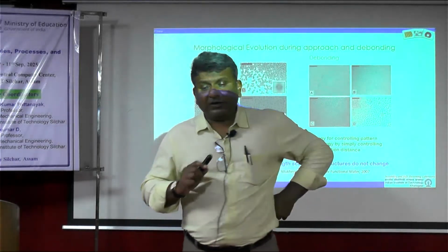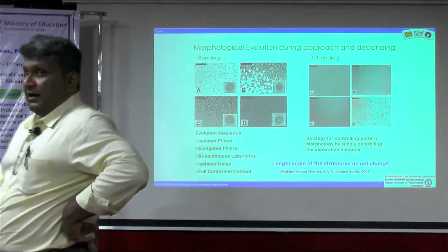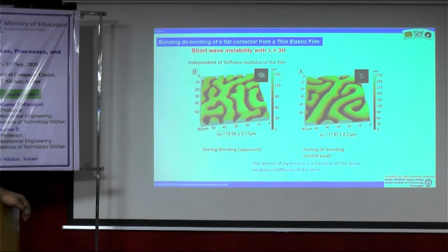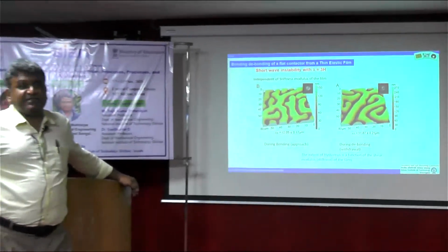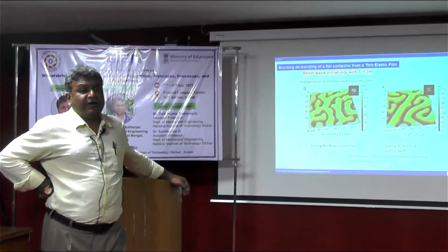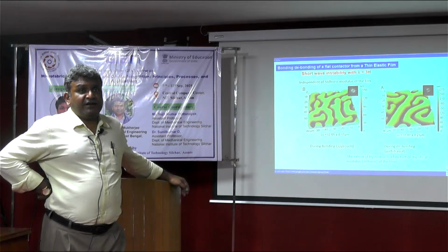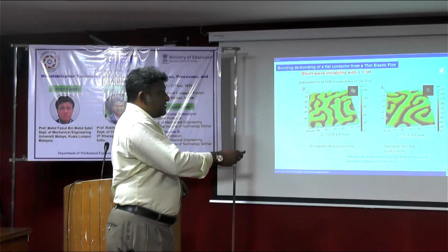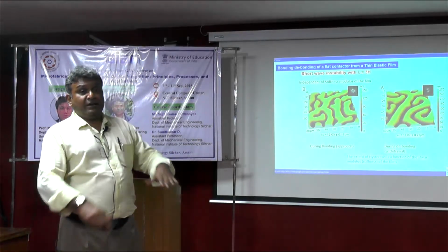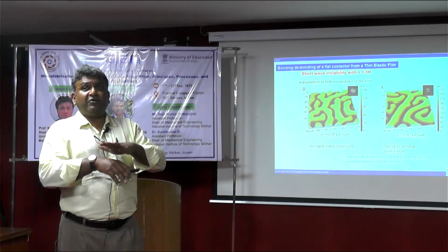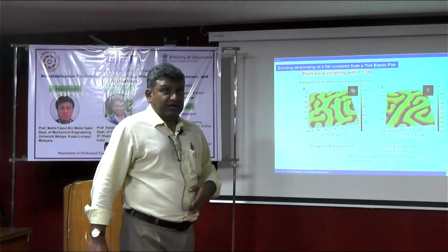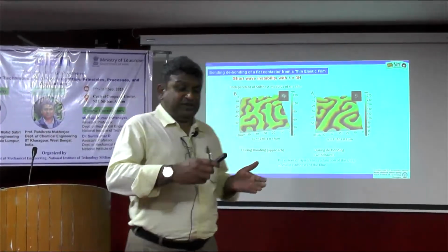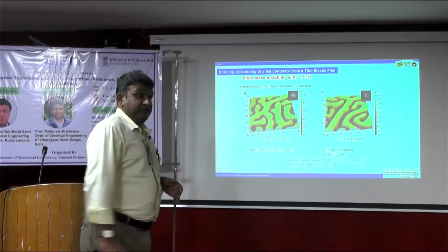But what nobody looked into was a more detailed AFM image of the same phase during bonding and during debonding. And now some of you who were present in my morning lecture are pretty good experts of AFM. So now you see the images look roughly the same, but what is different is the scale bar. While the features have a height of about 150 nanometer during the approach, exactly identical features appear during debonding, which have much higher feature height, right?